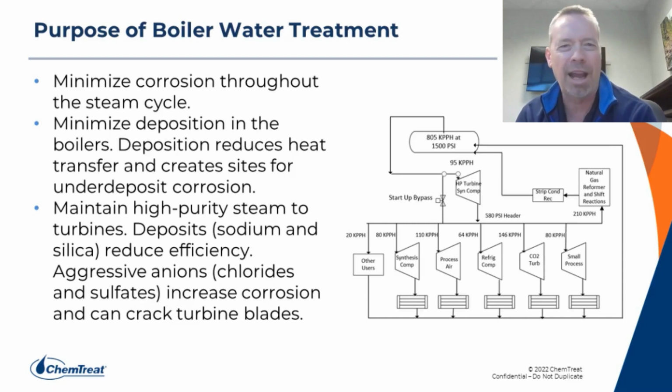We really don't add true corrosion inhibitors to the boiler system. Really, we remove aggressive and fouling ions like calcium, magnesium, and chlorides and sulfates and silicas. And then we reduce and remove oxygen via mechanical and chemical means. And we raise pH, and we really rely on the natural passivation at this higher pH and higher temperatures to do the corrosion inhibition.